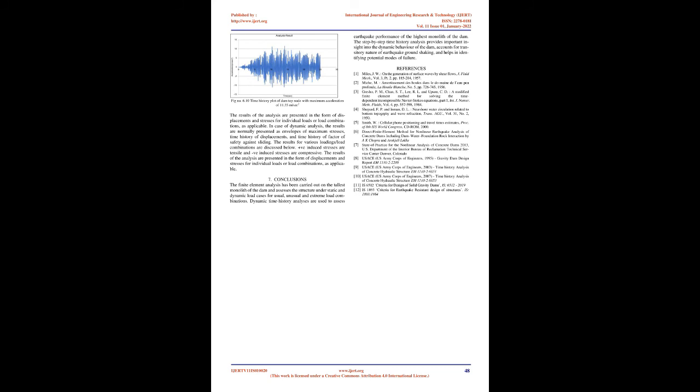Time history analysis has been carried out for load cases D, E, G, and H. Ground motion has been defined for 25 seconds with time increment of 0.05 sec. It infers total 500 time steps are considered in the analysis. Arrival time is considered as 0 seconds as acceleration value in time history curve touches maximum in time period of 0 seconds to 25 seconds.